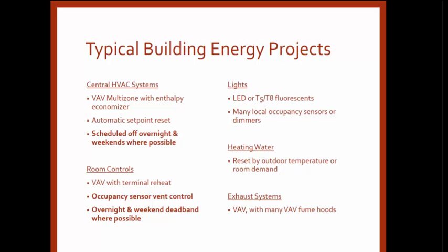This is a very high-level list of energy projects that our campus has engaged in for the last 15-20 years. Probably very familiar to most of you in attendance. A couple that are highlighted: we schedule systems off overnight and weekends wherever we have systems that allow us to do that. Another big one is occupancy sensors. In all the new buildings that we commission, or any renovations we undertake, we require an occupancy sensor, not just for lighting control but also for air control. In addition, we also do overnight and weekend deadband, again where our systems allow.